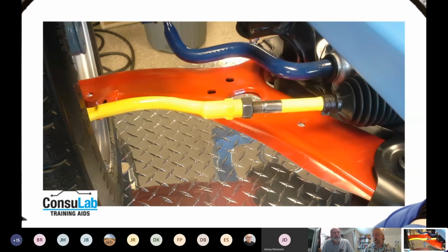One of the primary reasons for those long tie rod ends is because it was so long it had less linear movement as it traveled through its arc, so it reduced the amount of bump steer on those, or the toe change through suspension cycle, because it's unequal toe change that actually gives us the bump steer.